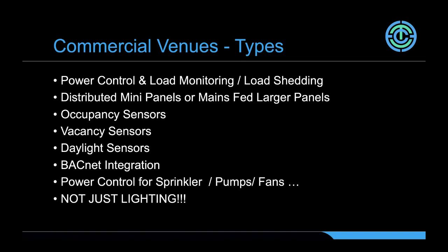We can also do data logging and recording of that power monitoring and load monitoring. So that allows us to, say, biweekly or monthly produce a report to a facilities operations manager, or even the, say, Ontario Hydro, that gives them real-time data on power drawn and allows them to work on incentive programs for both power rebates, as well as real-time information for being able to load shed when there's a demand.